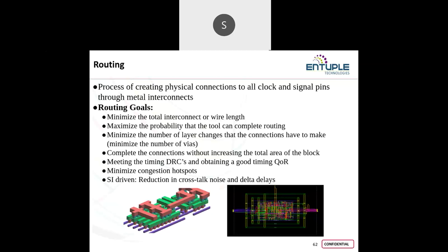Yeah. So now I am moving to the last stage, which is usually called the routing stage. So coming to the routing stage, what are we discussing? Routing means we will be considering the complete logic, as I have already told, the interconnections, or you can say the physical connections. The creation of the physical connections needs to be taken care of.